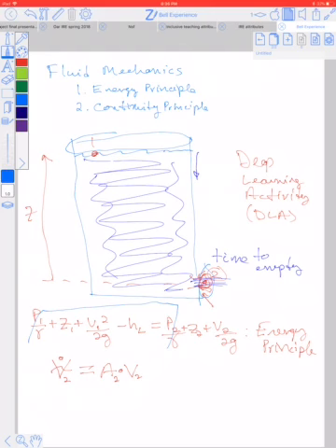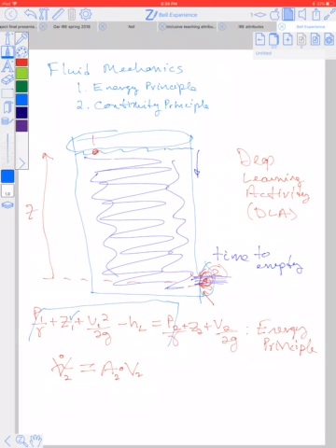The height at point 1 is the thing we can measure, and we are going to, at least on our first go-around, neglect the friction, call it approximately 0. And if we say that the height is equal to 0 at the hole, then when we measure, we can get the height at 1, so we can call the height 0.20.